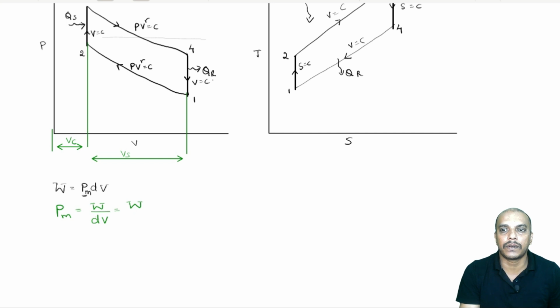Now, V1 is the total from the cylinder head to here. This is our V1, all right. Now, V2 is nothing but the clearance volume, from here to here. So, the swept volume dV can also be written as V1 minus V2. Let us call this expression 1.